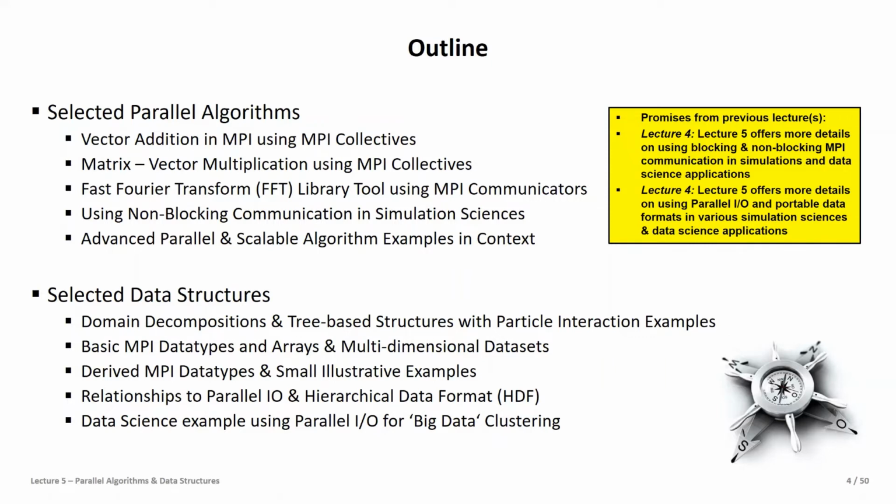Then, of course, when you dive a little bit deeper and think about what domain decompositions could be possible, we learned about this a little bit in lecture 3 already, and lecture 4 extended it here and there. But of course, we always had this more Cartesian idea of the world. We broke the ocean into blocky parts. What are the limits of domain decomposition? We learned about halo and ghost layers, how they have an influence on how you do your domain decomposition, and then think about perhaps particle interactions of long range and short range. You would maybe design a different structure, which could be a tree-based structure.